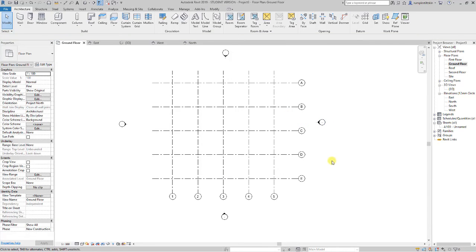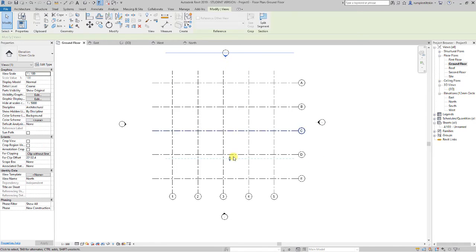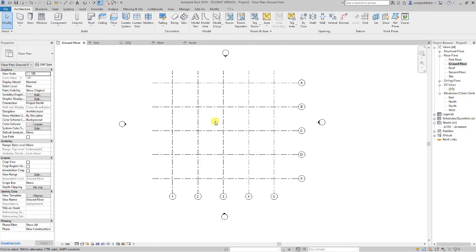And then if you can remember what I also need to do, the far clip offset for each of these, that's too short. So if I was viewing this elevation, it would stop at this point. So I need to drag that down. And just keep doing the same thing. So I create this visual box which is going to capture all the information inside this zone. Okay, so that's that bit. So 1, 2, 3, 4, 5, A, B, C, D, E. That's perfect.